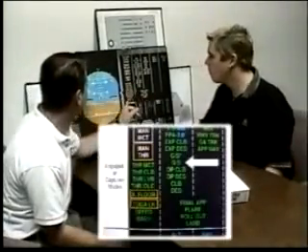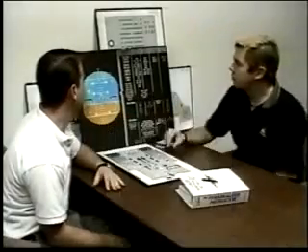We may need it for some type of climb, but the fact of the matter is it needs some kind of thrust in between typically, so it's going to need speed. Glide slope's engaged. What mode will you get in the auto throttle column? It'd be speed. It's just like a flight path angle, so it needs to use a varying range of thrust, so it'd be glide slope is associated with speed.